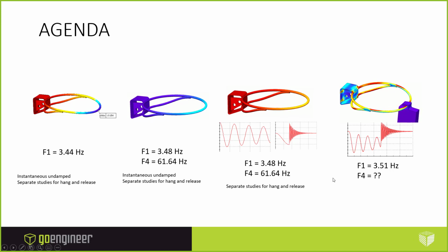Good luck deriving the fourth frequency that I was looking at from these other ones. I don't really have a twisting mode on here, so I'd have to impact it, create that, and excite that twisting mode, and then maybe I can do that same kind of manual FFT on there per se, or a direct one, and I might be able to derive that one. But this study doesn't show me that, the way I set it up currently.